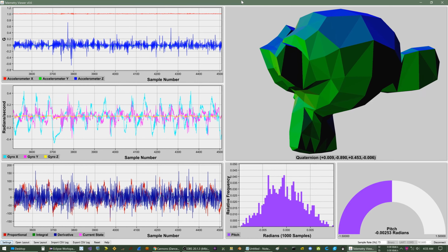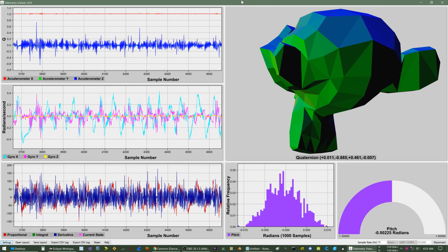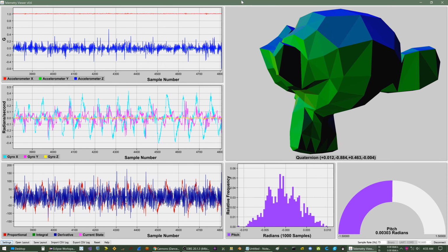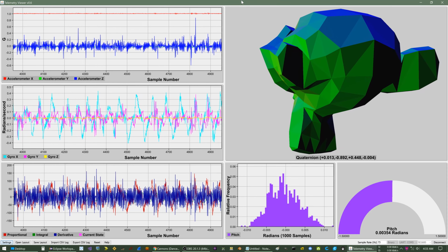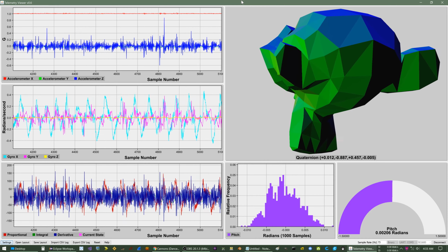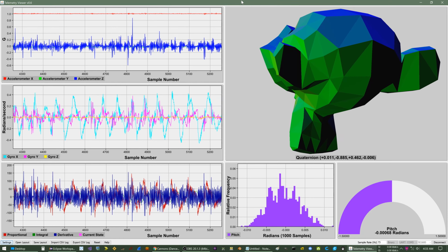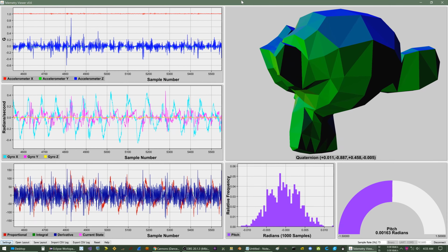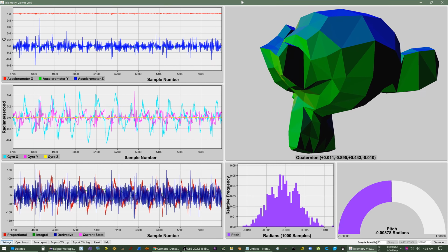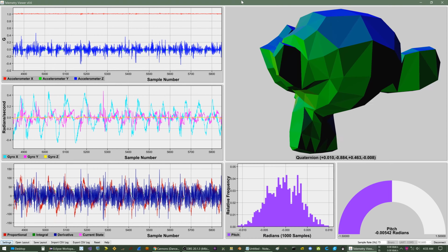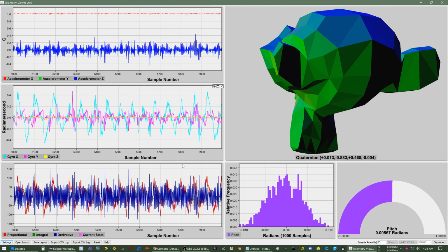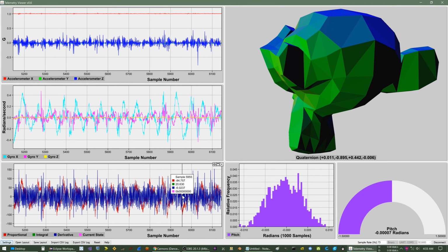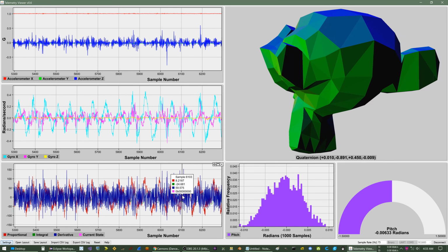In binary mode, I decided to call it bitfields, but that may not be the best name for it. You can have a struct, and it can be a packed struct where you specify how many bits are used to store each element of the struct. It supports 8-bit packed structs that you can define as either booleans or enums, and then it will show you events on your charts when those booleans or enums change.